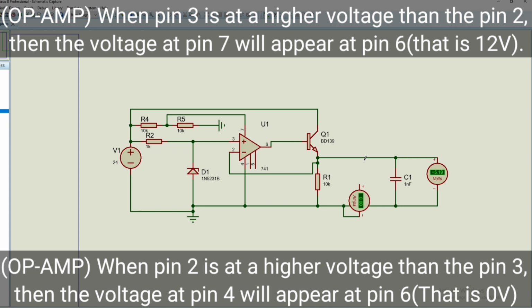Now I will add some load over here. Here is 5 ohm, so the maximum current should be 1 ampere and the output voltage should be 4.5 to 5.5. If I run this circuit, you can see I have 4.6 volt over here and 0.92 ampere current being drawn through this circuit. So this is very close to ideal, because there is only a 0.4 volt drop at this higher load. Thank you.